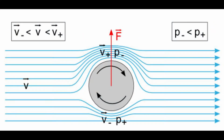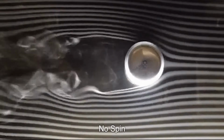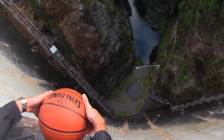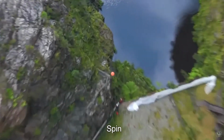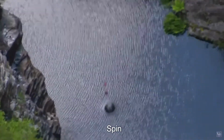The Magnus effect is a phenomenon in which a rapidly rotating object in a fluid experiences drag and lift. The lift created by the spinning object is perpendicular to the direction of the flow and the axis of rotation. This force significantly affects the flight of objects such as golf balls and baseballs. Shown here, a spinning basketball dropped from a significant height creates enough lift to yield a nearly horizontal flight path. Pressure and velocity differentials are crucial for lift generation.